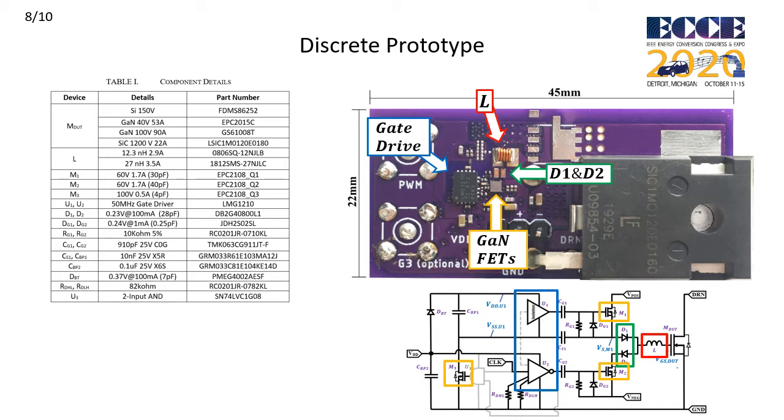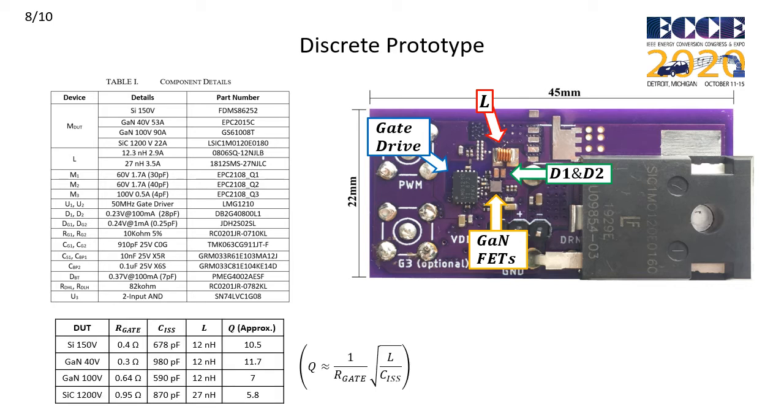The driver's total component volume is a little over 17 millimeters cubed, with 55% of that being the dual gate driver, about 28% being the inductor, and with the GaN-FETs consuming about 8.5%. The rest is made up by small diodes, capacitors, and resistors. The driver was used to control 4 different commercial FETs, one silicon carbide as depicted, and 2 gallium nitride.